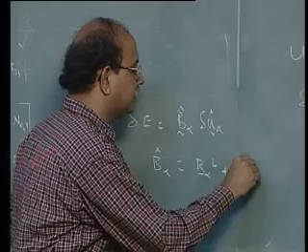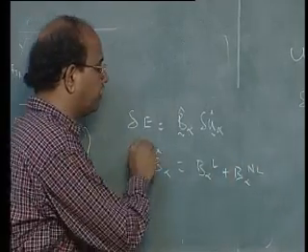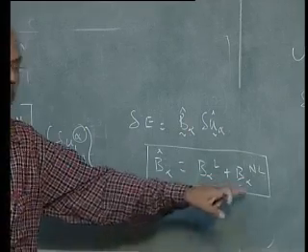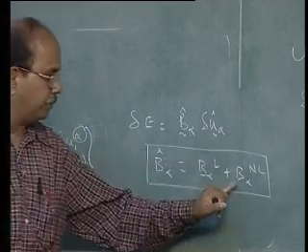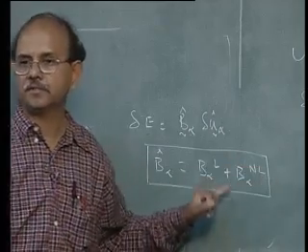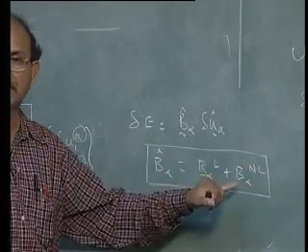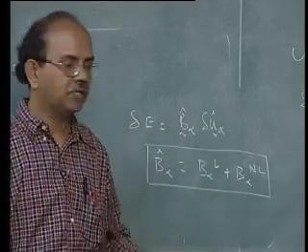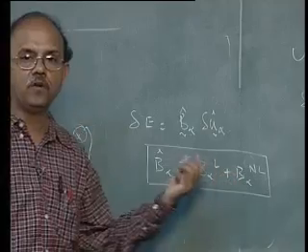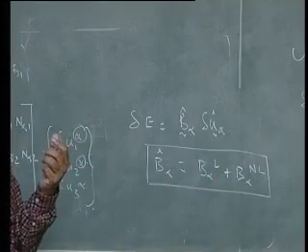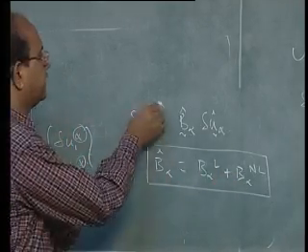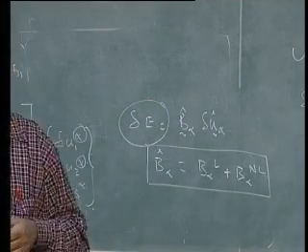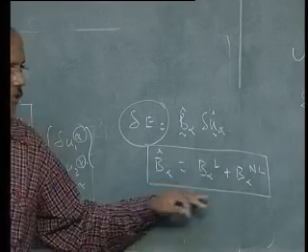Actually, you can see that this can be split up into 2 terms, a linear B alpha term and a nonlinear term. So this BNL, a very famous term, is the addition to BL. BL is what? Our old B matrix, which is actually the one that converts delta epsilon ij, which we had seen, to delta E ij. Okay, so this is what we are going to use.